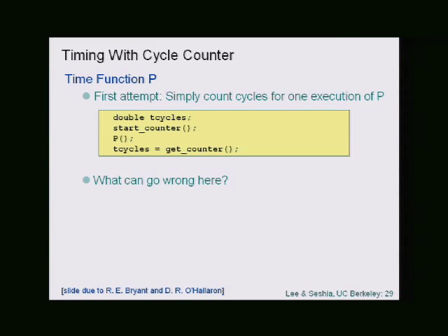Yeah, so the time taken by a function call can also affect how long this measurement takes. We implemented this as a function call. Of course, you don't have to implement it as a function call even if you want your code to look pretty. You can write it as a macro in C, and that way you avoid the overhead of a function call. It's a good point.